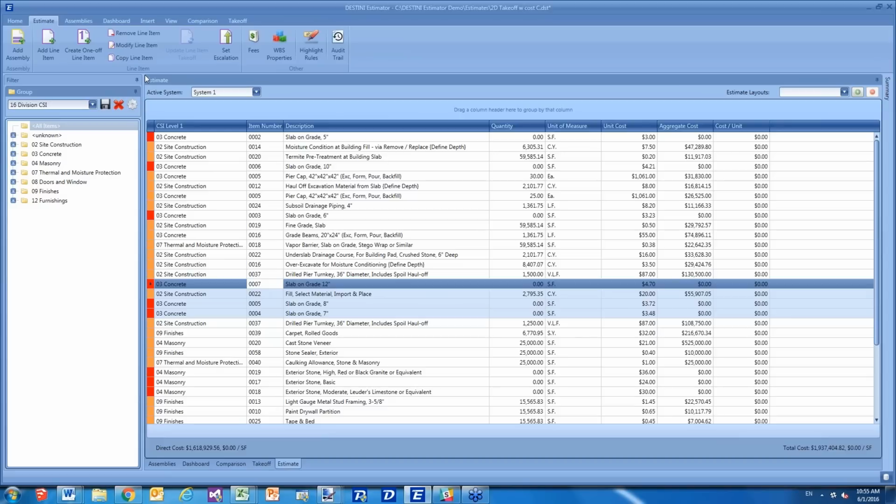Can you update the estimate automatically when you get new 2D drawings, much like the way it was demonstrated in 3D? Yeah, so the way that we handle 2D is it's kind of like a slip sheet where you specify the new drawing. So in the takeoff, you would click that update file. In this case, this would be a 2D drawing. You'd find the new version of that particular drawing that you wanted to update, and it would slip it underneath. So the quantity takeoff objects would stay in place. The new drawing would be slipped underneath, and you'd be able to handle the adjustments accordingly.